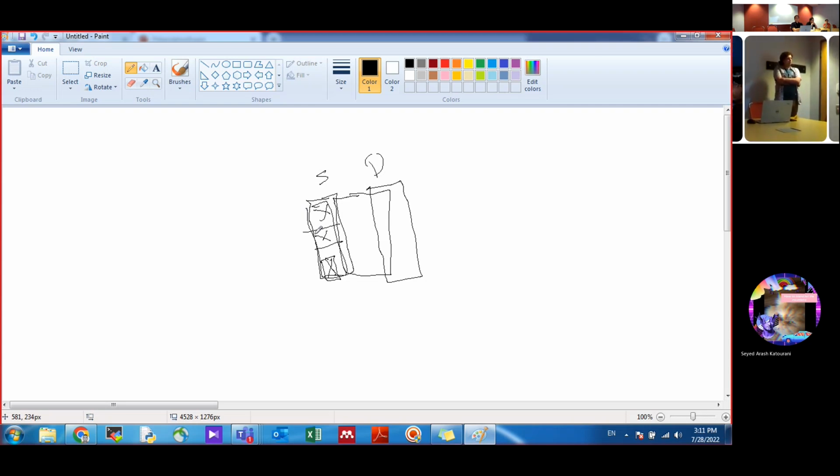Because what I do is I use, for example, metal 2 for horizontal wires. So if your source is metal 1, you do metal 2 all over it, and if you have another transistor here, you block your metal 2 with these wires. Good. But what is the purpose of covering it all with wires? Because when you have something like a big one, it's not going to be.